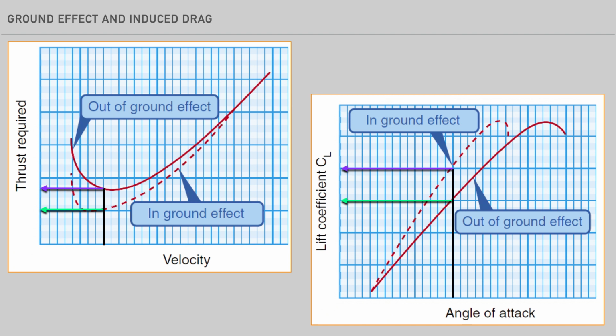From a practical standpoint, the airplane can become airborne at a lower airspeed. However, if it climbs above ground effect, the coefficient of lift may decrease due to sudden increase in induced drag, and the airplane may settle back on the runway. To solve this problem, rotate at the manufacturer's recommended airspeed, or, in the case of a soft field takeoff, lift off at a lower airspeed, but remain in ground effect until you build up sufficient airspeed to begin the climb.